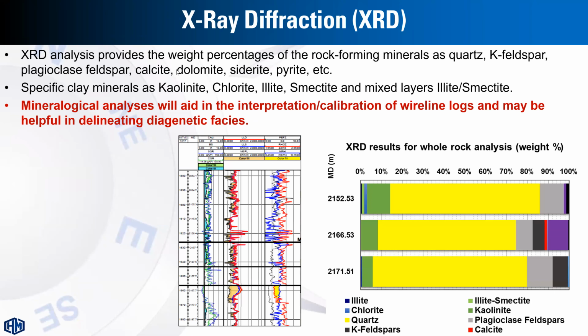Just an application of XRD on core samples at different depths. So XRD analysis provides the percentage contribution of the different minerals such as quartz, feldspar, and different clay minerals like illite, kaolinite, and so on.